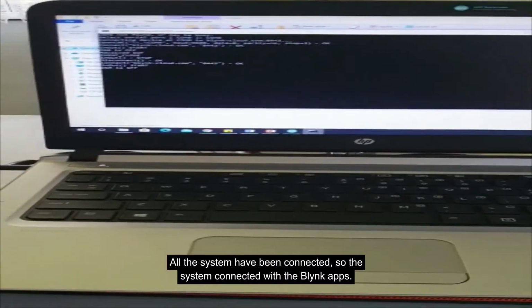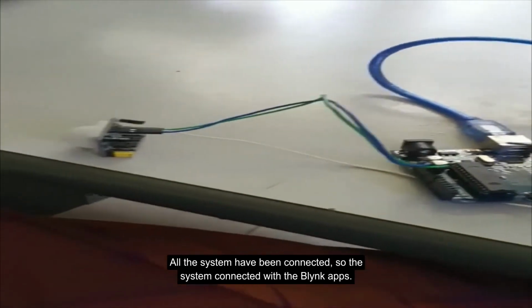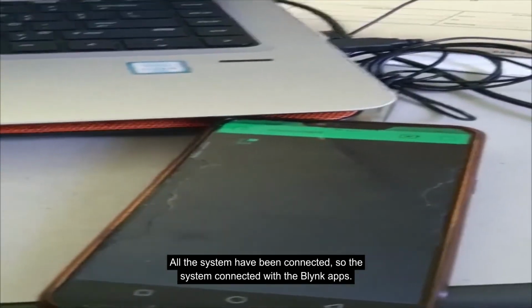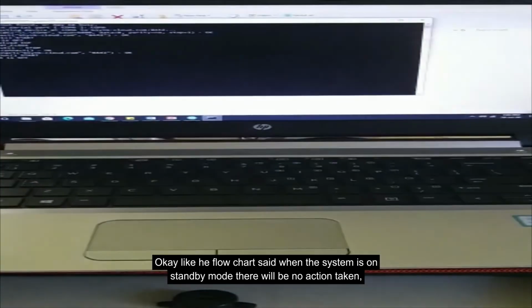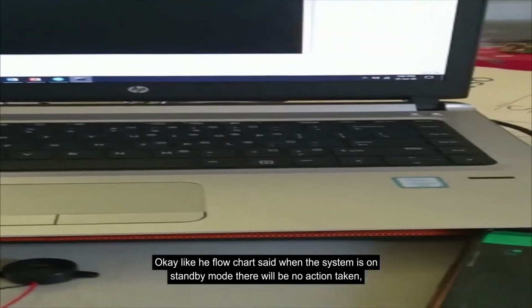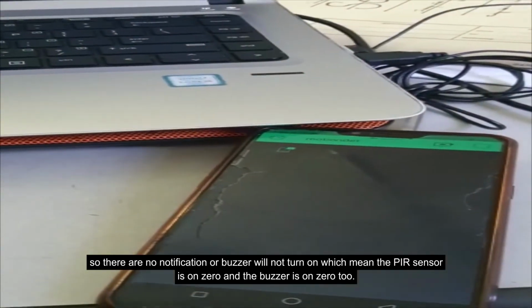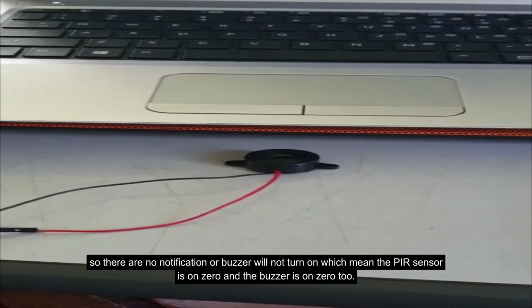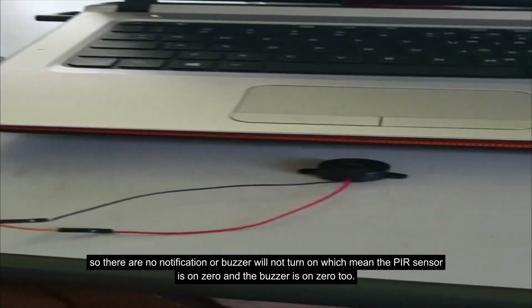Okay, all the system have been connected. So the system have been connected with the Blink app. Okay, like the flowchart said, when the system is on standby mode, there will be no action taken. So there are no notification or buzzer will not be turned on, which means the PIR sensor is on 0 and the buzzer will be on 0 too.